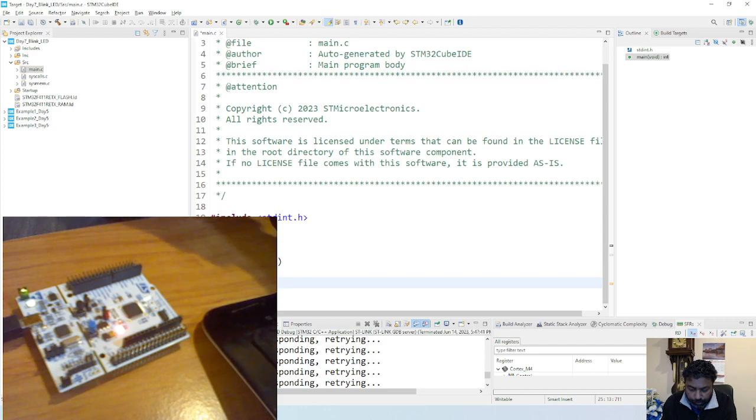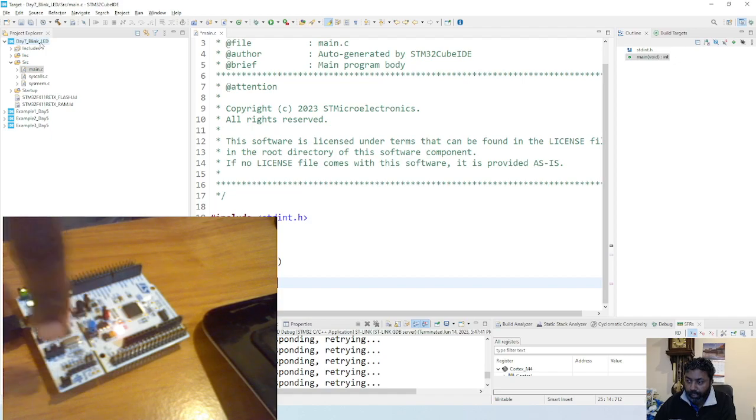So it's just set as return. And I'm testing to build the project to compile. This will create the .elf file, the executable linker file, which is very important because that's the file you're going to program and send to the targeted board for your program to work. So .elf is very important. It has to be error free and mostly warnings free. Warnings are not a big concern, but you need to make it error free, otherwise your code won't work.